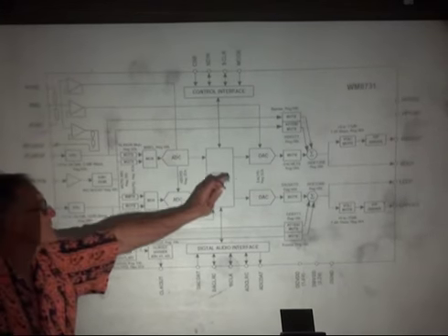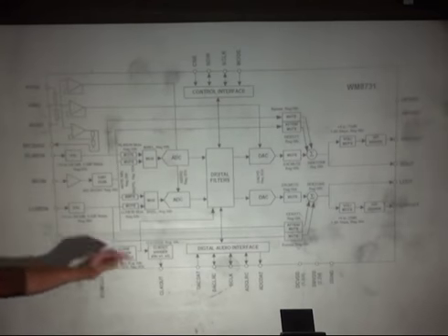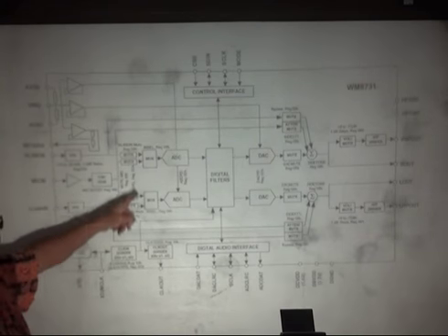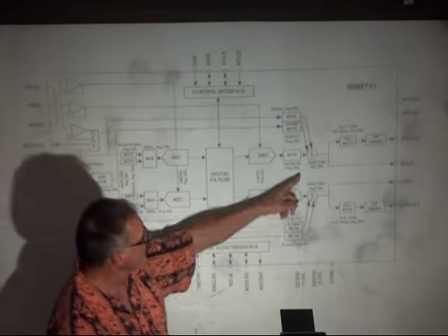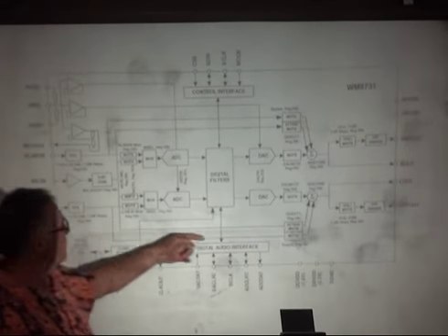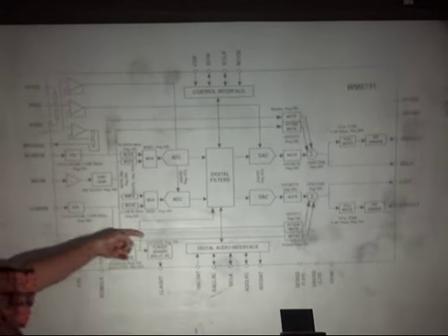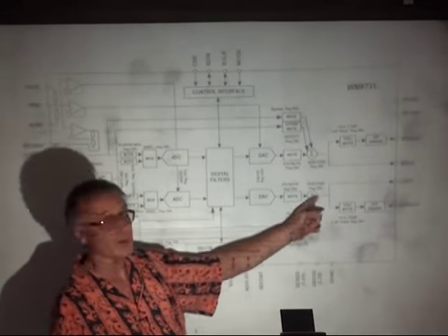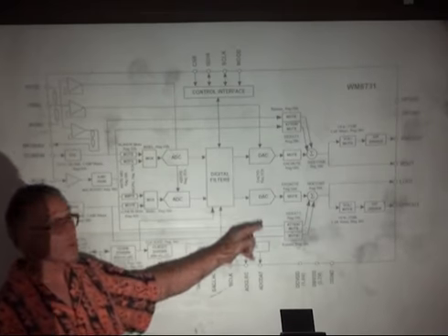All of these settings are controllable. Volume in, mic boost, mutes of various sorts at the output, analog bypass that allows you to just take the input and take it to the output without going through the digital filters, so that you can actually mix the raw input with the filtered output if for some reason you wanted to do that.